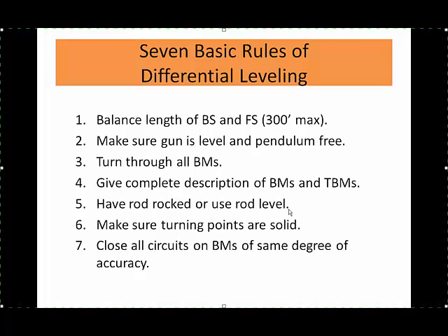The purpose of the description is to enable a complete stranger to find your benchmark. Fortunately, when surveying in strange cities, strange to me that is, in different states, I have been the beneficiary of well-written benchmark descriptions that have enabled me to find things I've never seen before that were even buried inadvertently.